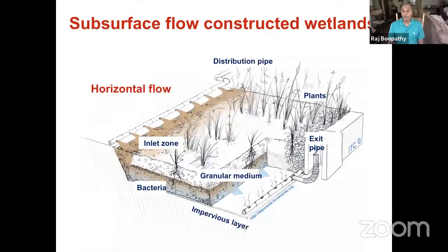Okay. Now there's also constructed wetland, which is becoming very, very popular in European countries. And you basically construct this wetland in different cells, and the wastewater comes in, doesn't even go through sewage treatment. It goes straight into this constructed wetland. This is where most of the treatment takes place. And of course, it's highly engineered. A lot of plants grow in there, and it just percolates down, and the waste is collected after it goes through. And you can see the difference in BOD and solids that come in here, and what is coming out in the effluent of the system.